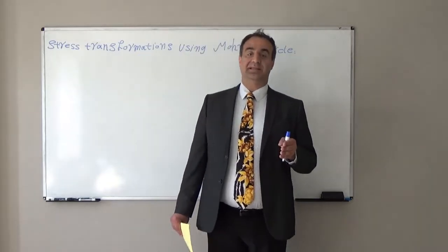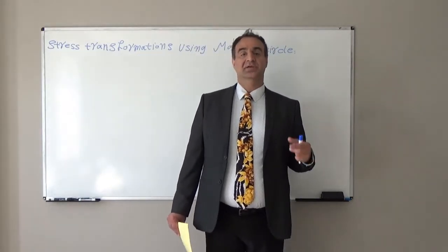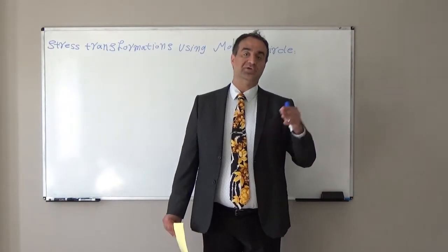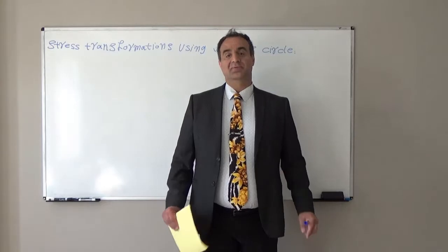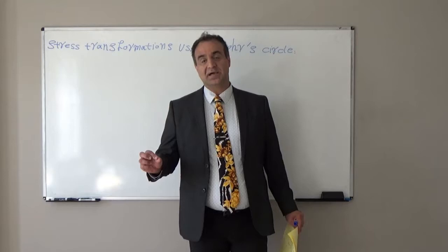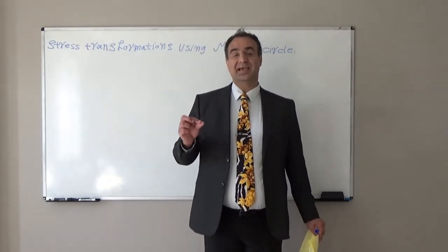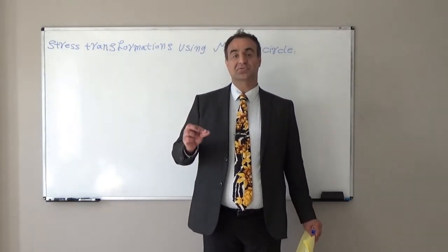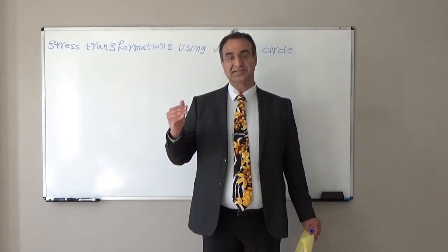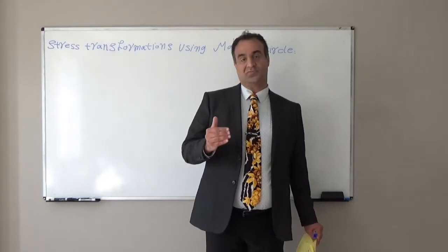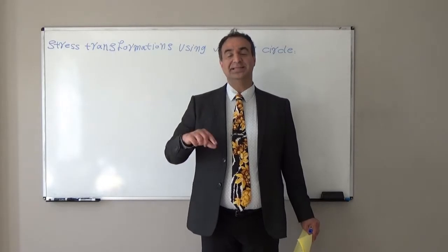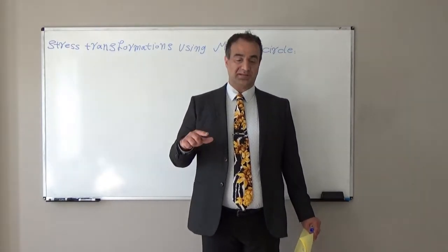In order to find stress in another direction, we should be able to transform stress from one direction to another direction. Whenever we want to design any structural member, we should design to the maximum stress. We should find maximum stress and compare that maximum stress in that member with the allowable stress. So we should be able to find stress in any direction or any orientation.